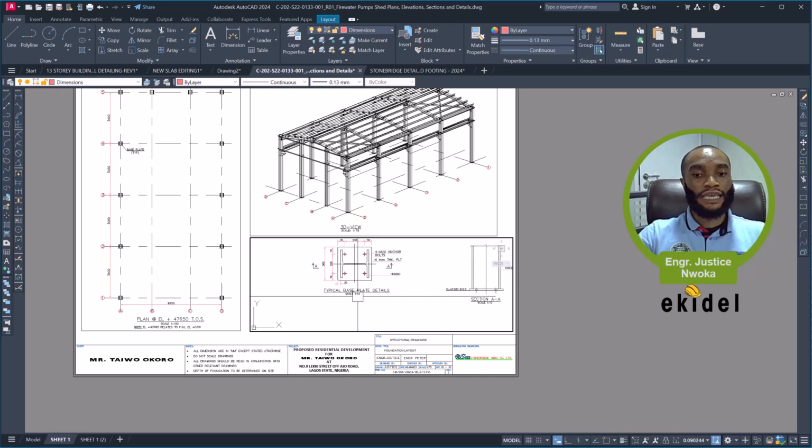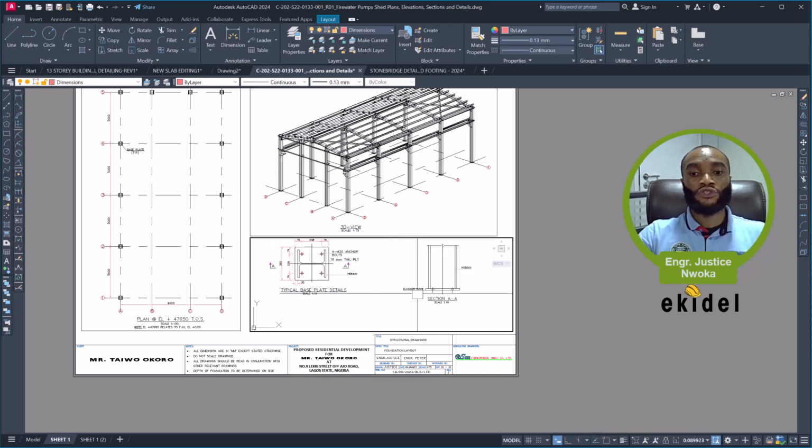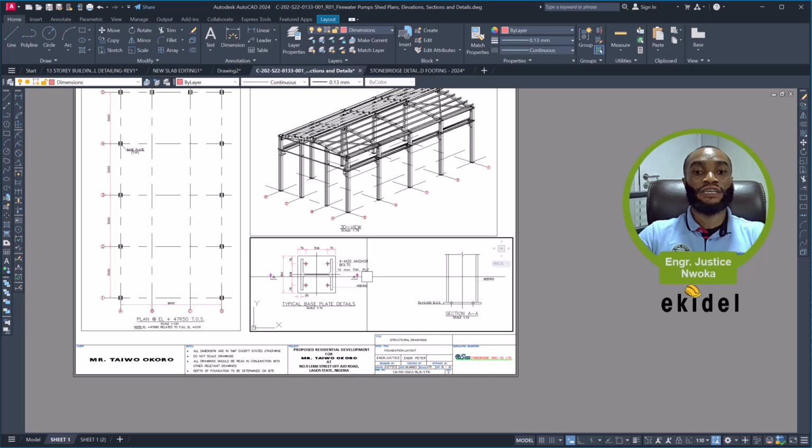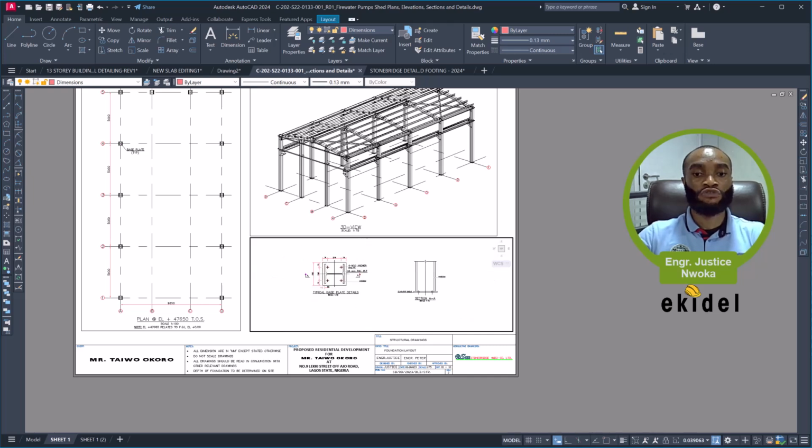You can see there 1 to 10 and also 1 to 10 here, and I'll then come like this and type Z, enter 1/10 SP, and press the Enter key. That's fine. You can see my drawing is now zoomed. So even if the drawings were like this before, once I type in my scale factor, it automatically brings the drawing out.